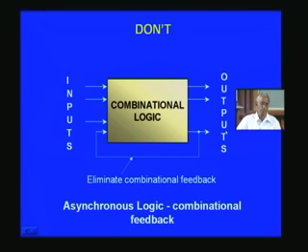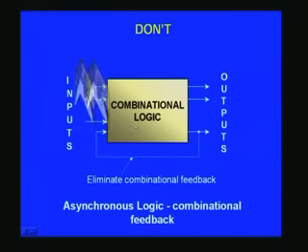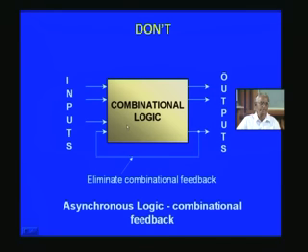When you use the synthesis tool, this is not permitted. It will give a warning or error message, and perhaps you can veto that and go along, but ultimately you will end up messing up the whole design, for the simple reason that your design will not work on the ASIC or FPGA that you have ultimately done. That's the reason why we should stick to these RTL coding guidelines, without which you won't get a working chip.